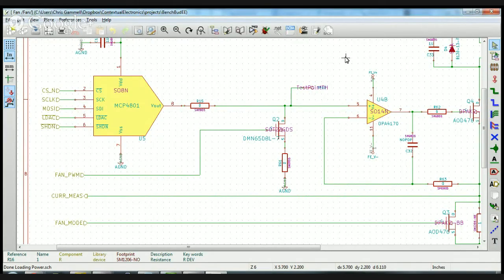Okay. So then you're not going to actually use that as a PWM, right? I can use it as both, right? If I want to use it as a PWM, I just drive the DAC to have its 4-volt output, and then I pulse it like I normally would.